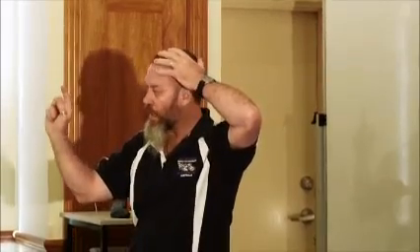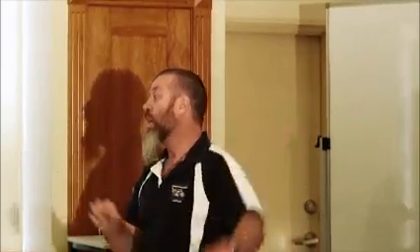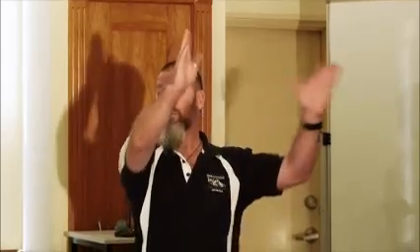Wind region C is the 50 kilometres right on the coast, and I think it starts up at Bundaberg and runs right around the top, right around to Darwin, and right down to, I'm not sure, somewhere further down south. And then there's wind region D, which is over in the Carnarvon area in Western Australia. And it's the highest risk because it's about cyclones.